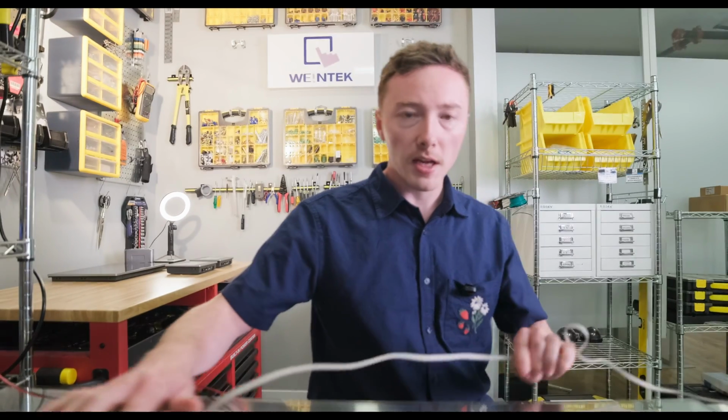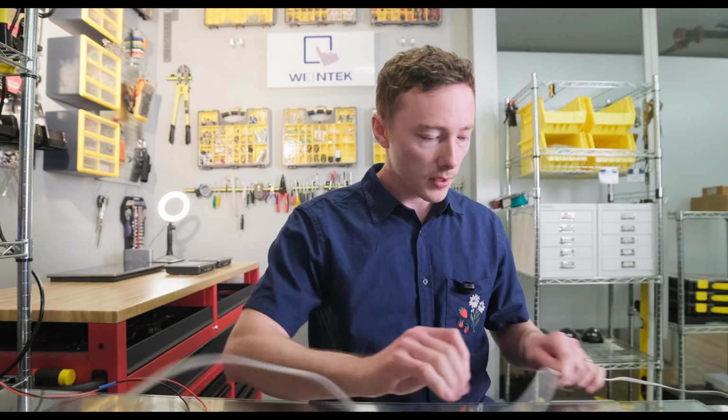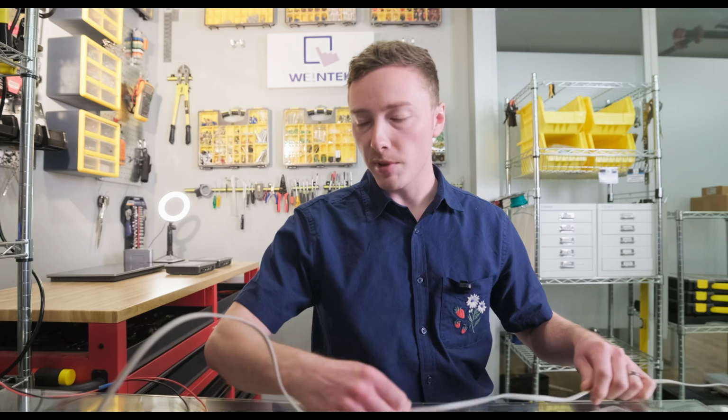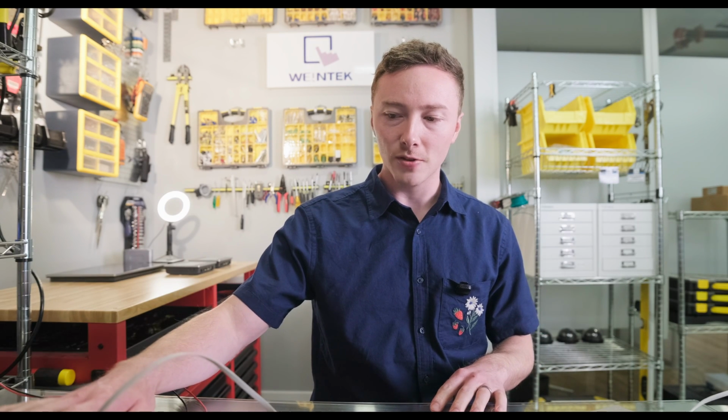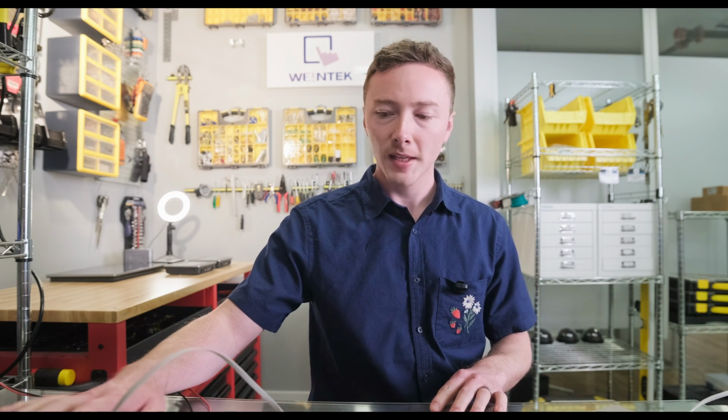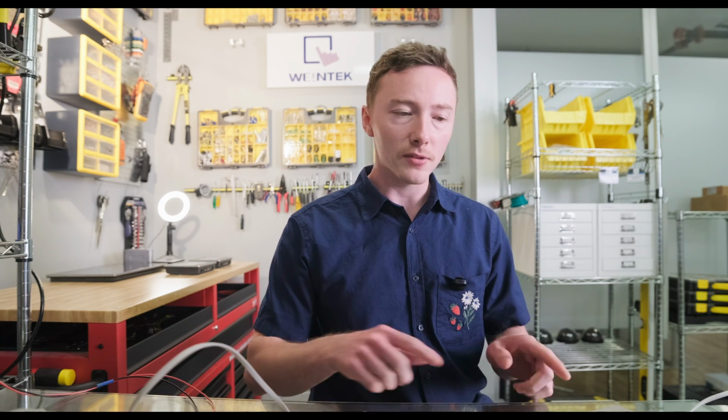Now, the one thing I'm not going to show in this tutorial is setting the IP address on this device. It's already been set. I'm going to assume, if you're looking to connect the two, that you've already set the IP address on your Micro 850. So mine's at 192.168.1.90, so you'll see me reference that IP in the video here.